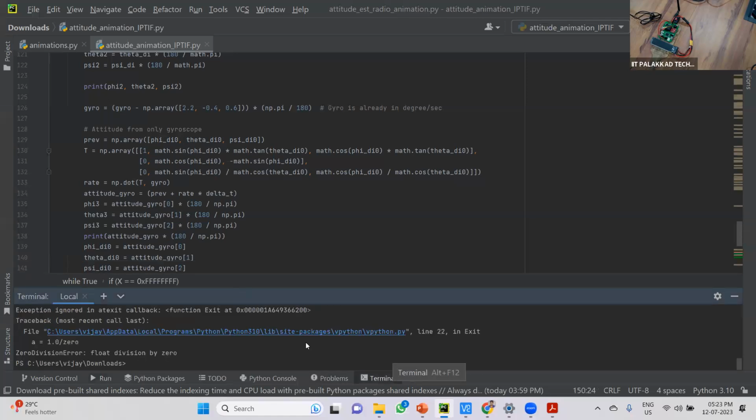Previously we discussed that we are adding filters, right? So will those filters help in avoiding the noise that we get through the linear acceleration, the accelerometers? Yes, the filters will help. Like a complementary filter, what we have to do is, for every sensor, first initially we have to apply a low pass filter. You need not take a very small bandwidth. You can take a little high bandwidth.